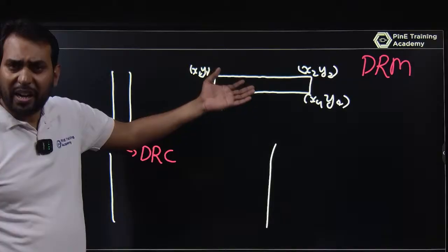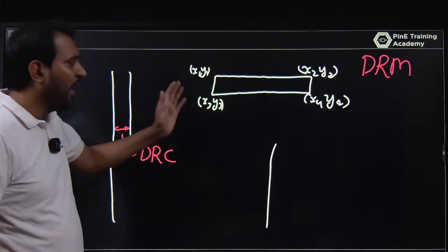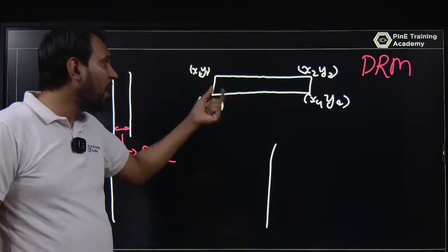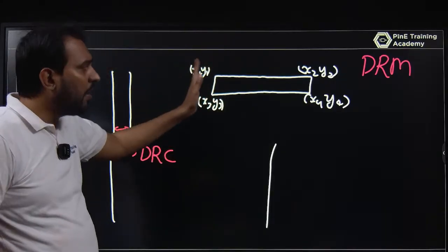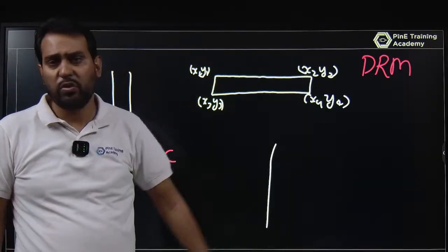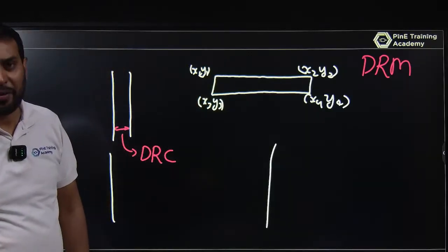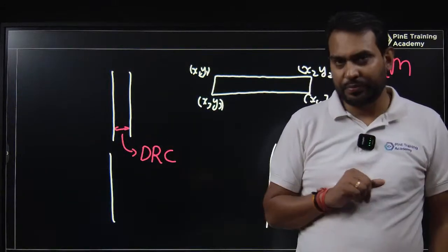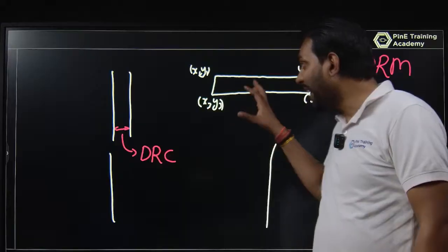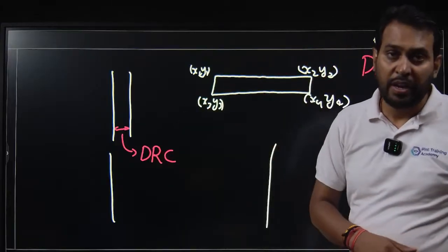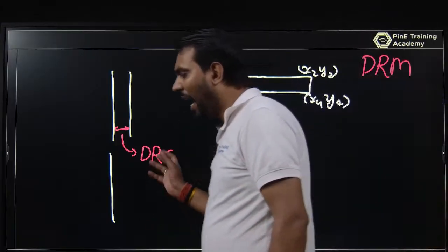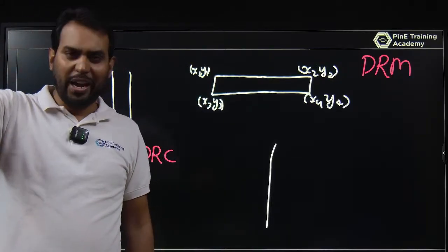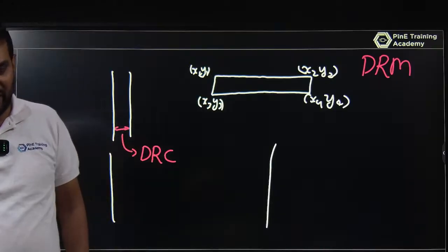And it has any metal. In terms of origin, the description is such that metal one follows from x1 y1 to x2 y2 to x3 y3 to x4 y4. It makes one rectangle. So that binary file has data in terms of coordinates. In terms of data, you have a MOSFET. Everything it has, and similarly this file will be stored in a foundry, and the foundry will fabricate that IC.